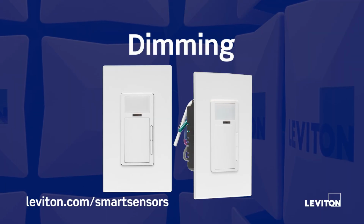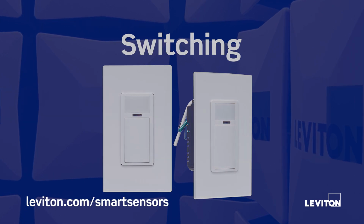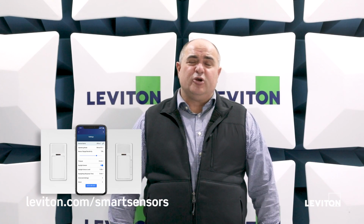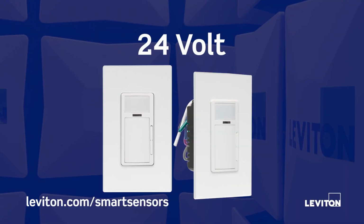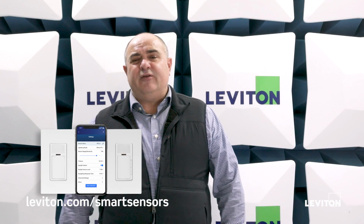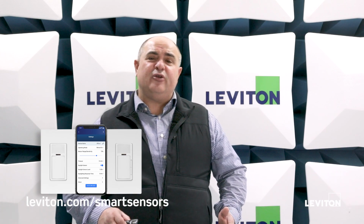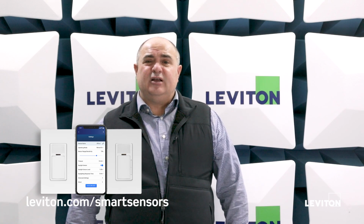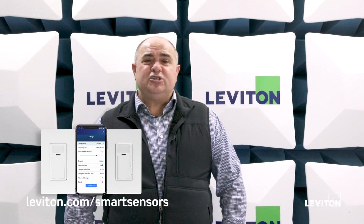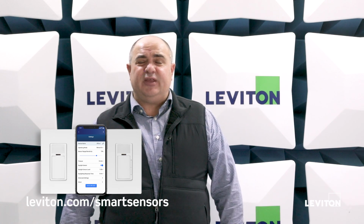And again, we have it available in both dimming and on-off switching options. We have the 120-277 volt version of it that works with 0 to 10 volt dimming. And then we also have a 24 volt version of that. And one of the things we need to understand is that both in our multi-tech version as well as our passive infrared version, not only do we have the 120-277 version of the 0 to 10 volt dimming, we also have a 24 volt version of it where the switching portion of the device is actually set up to switch at low voltage.